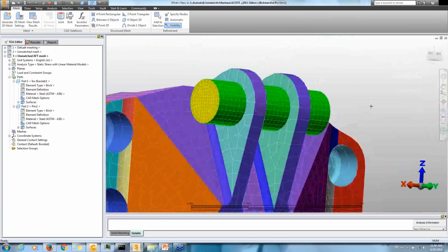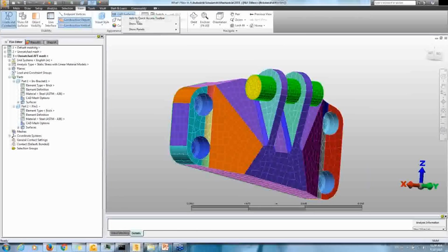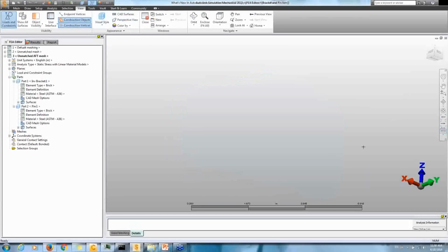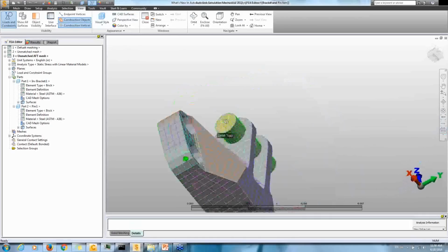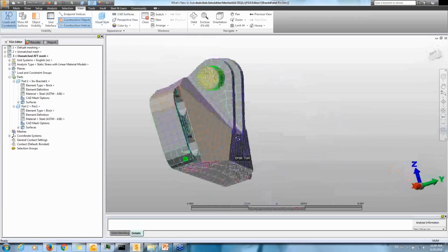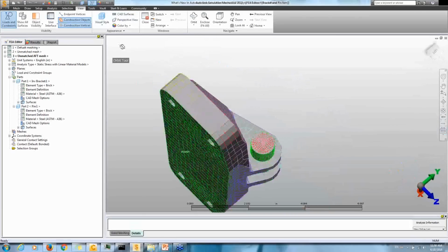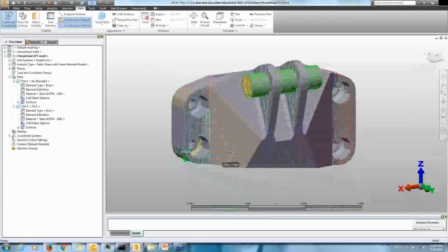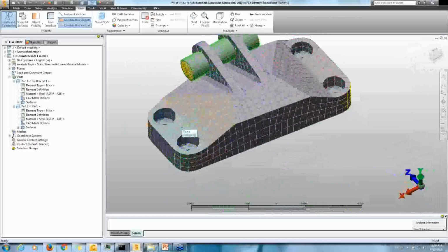And this is true also for fillet-looking objects as well. When we look at all four fillets, we will always see the same rectangular mesh around those edges. Marwan's showing one over there on the bottom left, but all the fillets should have the same look and feel without the introduction of the triangular elements. As much as possible, this option will try to give us the most uniform looking rectangular surface mesh. And as we all know, a good surface mesh will yield a good solid mesh at the end of the day.